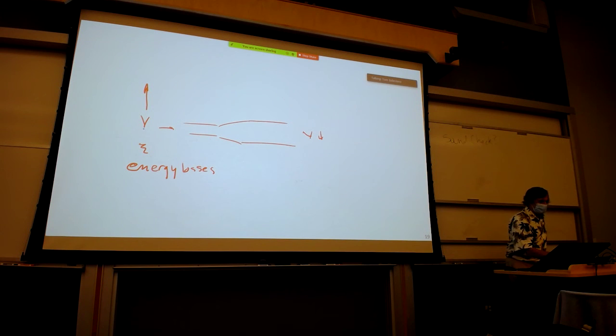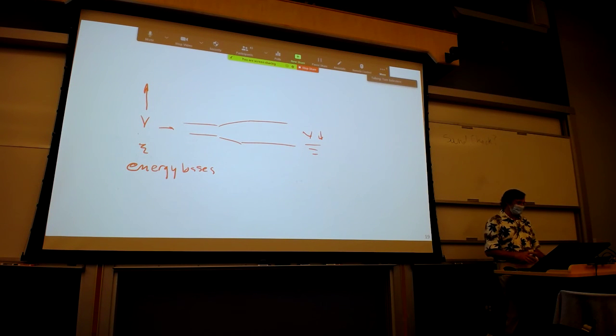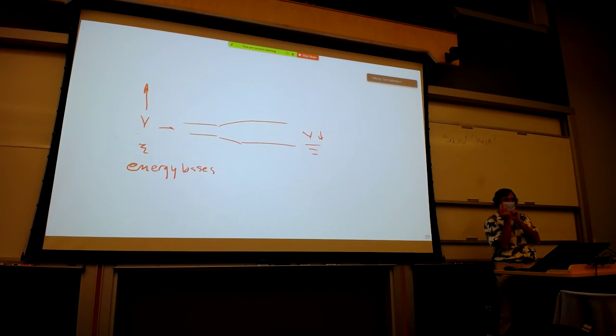And so typically in distribution systems, what we try to do is minimize velocities. And by minimizing velocities, you can move water over enormous locations, cities like Philadelphia, Pennsylvania, New York City, Boston. By keeping the velocities really low, you're basically just using pressure to move fluid around. And that's what we're getting into next class. We're talking about energy, and this is all going to come to a head. There are 3 laws of fluid mechanics. We just finished the continuity equation. The other 2 laws are energy and momentum. And we're going to do energy next week.